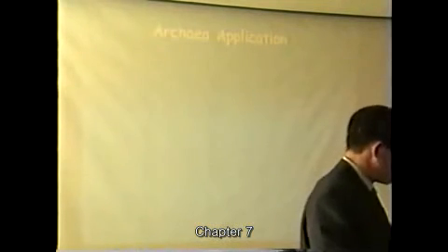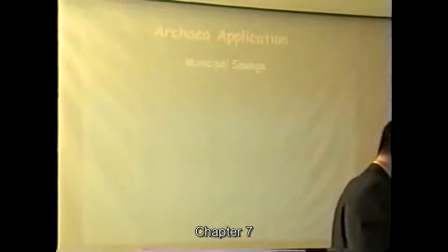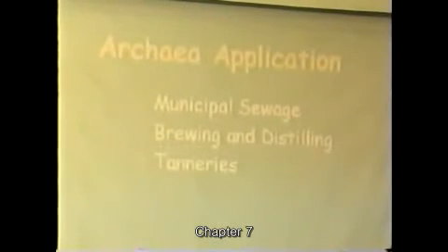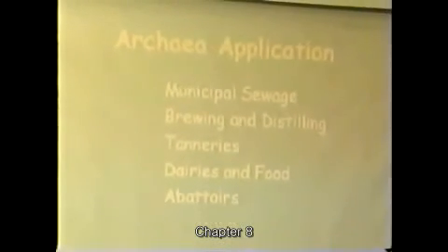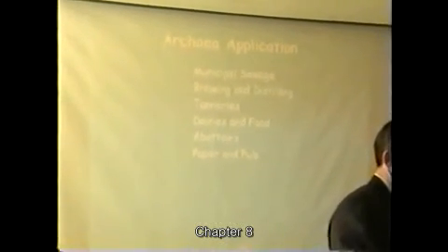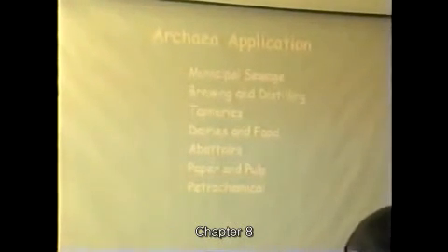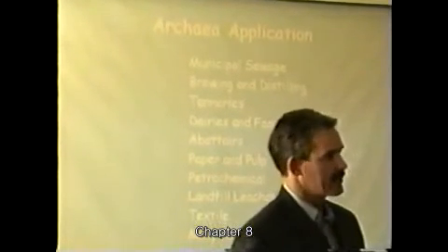Where do we apply Archaea? Basically everywhere. Anything that's biodegradable: municipal sewage, brewing and distillery effluents, tanneries, dairies and food industry waste, anything that's very high in COD, abattoirs, paper and pulp industries, all those recalcitrant compounds, petrochemical as I discussed, landfill leachates, textile, and anything basically that is biodegradable.